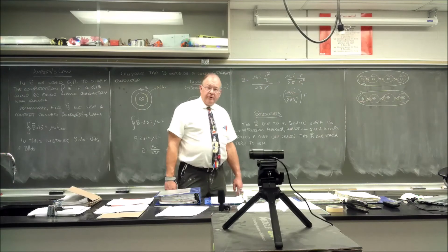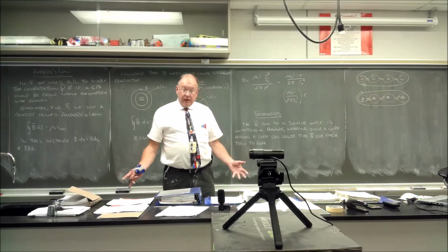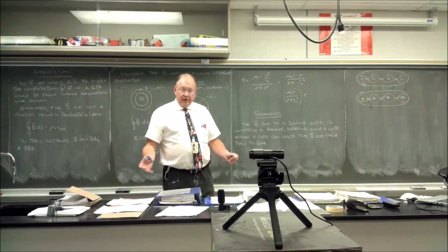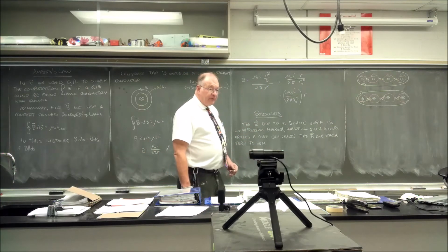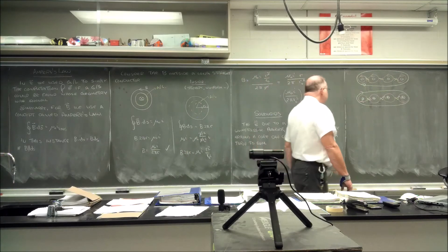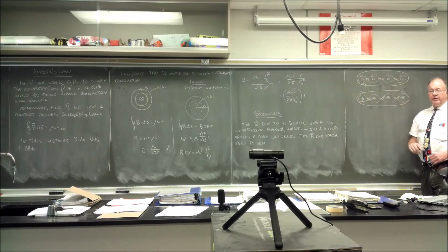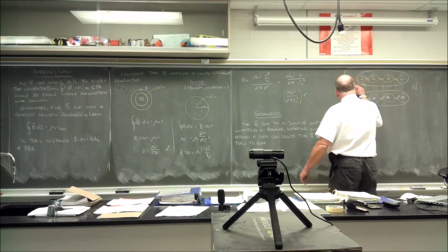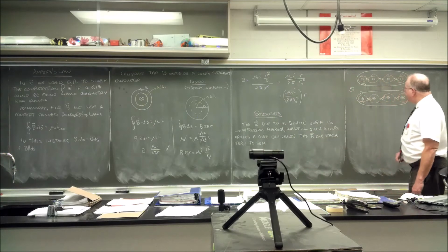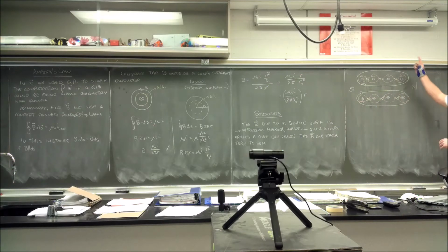And this leads us to the second application of the right-hand rule, forget these numbers, okay? And again, it only makes sense, you can mix them up. We used the first version already. The second version is for coils. If you put your fingers in the direction of the current, your thumb will point to the North Pole. So we get a North Pole here and a South Pole here. And be careful, you might say, oh, well, sir, the field lines go from the north to the south. Yeah, okay, sure, but that's on the outside, not on the inside.